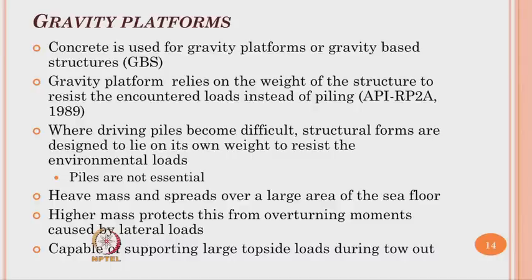They are briefly called GBS. GBS stands for gravity based structures. A gravity platform, as the word suggests, relies on the weight of the structure. The structure is so large and highly massive that it resists the lateral loads purely on its self weight. There are instances and structures where pile foundation may not become essential.